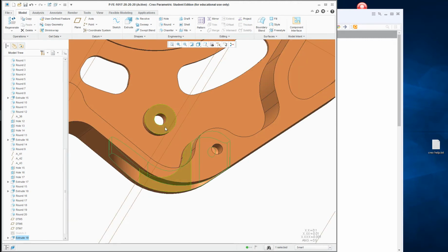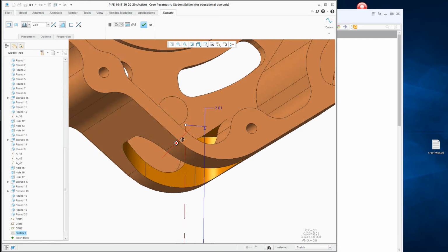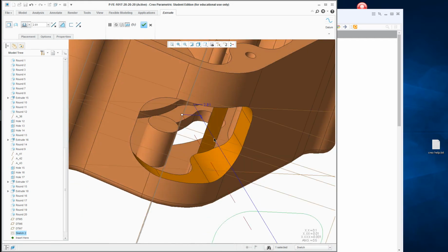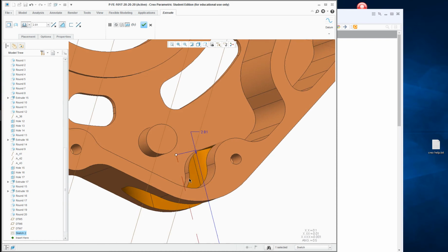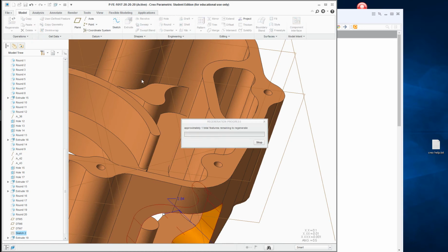I cut the boss a little bit, so on scenarios like that, edit the sketch, edit the depth on it, and just don't go all the way in. And right there you can see where it's getting a little bit of a wall hang up over here on this. So just adjust your things minorly, and there we go. So we've got that cut.